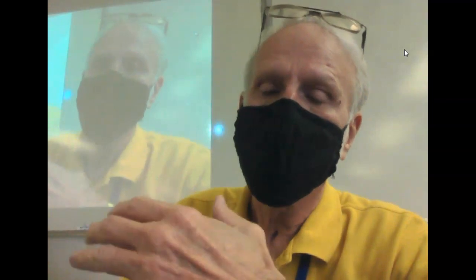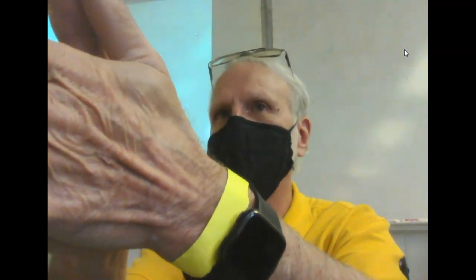Well, it will arc, but it helps extinguish the arc, but you're moving real fast. So the analogy I use is when you're in the swimming pool or something and you have your hands together and you open them, what happens? The water flows in between them real fast. So it has a tendency to extinguish the arc the faster that we make them and the faster that we break them.